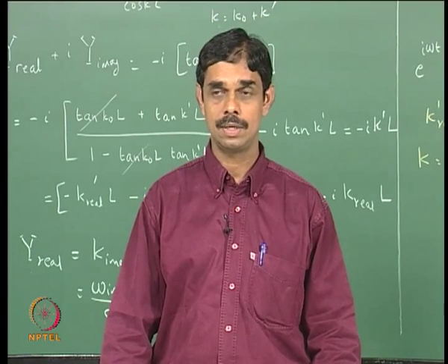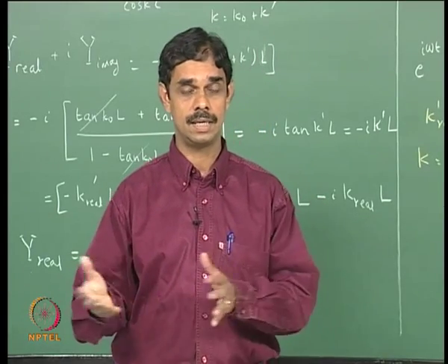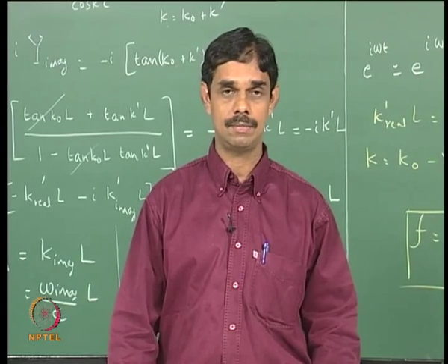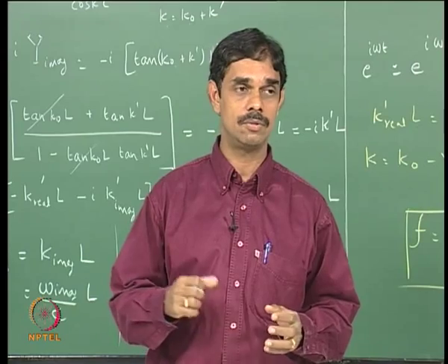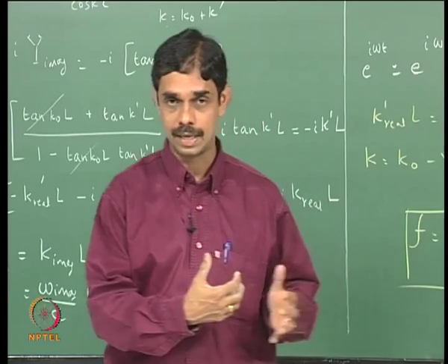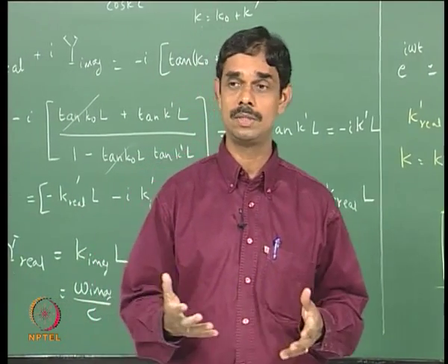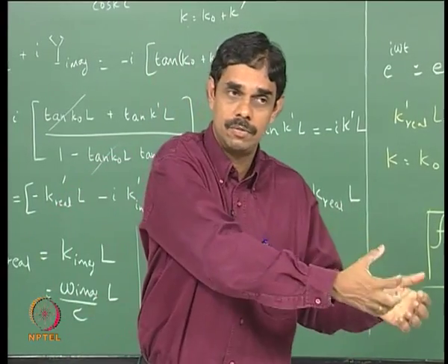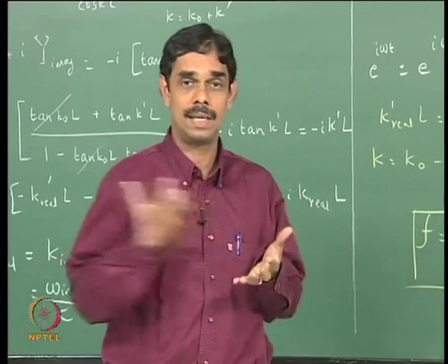and so aluminum also burns and forms alumina which is initially molten, and as it goes through the nozzle it may start solidifying. These alumina particles have a certain size and they have a certain drag, because when the particles are in a sound field, the particle will try to move along with the sound field, so the sound field will drag the particle, and in the process the sound will lose some energy, because when it is trying to drag the particle, it is giving some of its energy to the particle or the droplet, so it is actually losing and the particle is gaining energy.